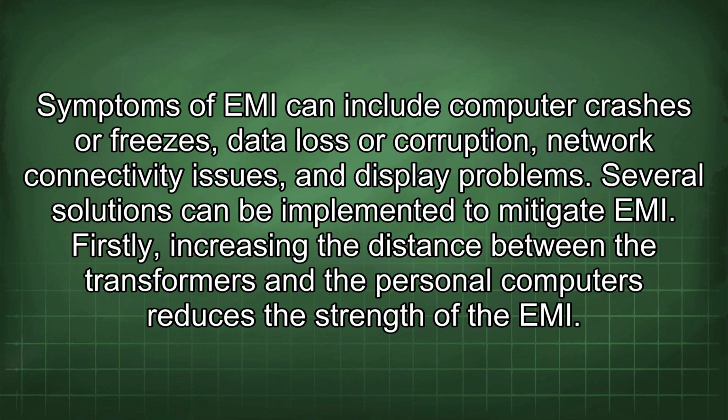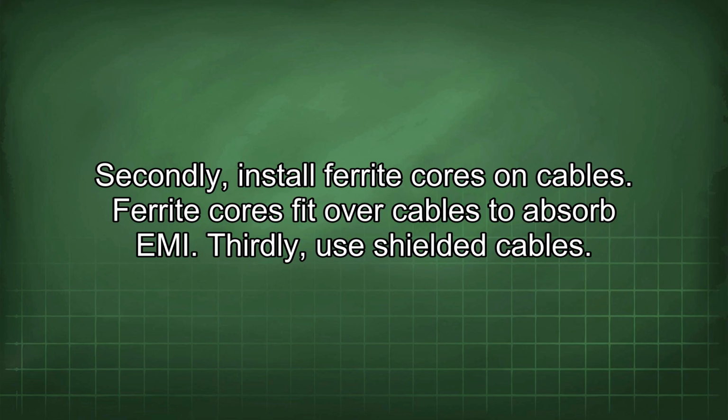Several solutions can be implemented to mitigate EMI. Firstly, increasing the distance between the transformers and the personal computers reduces the strength of the EMI. Secondly, install ferrite cores on cables. Ferrite cores fit over cables to absorb EMI.